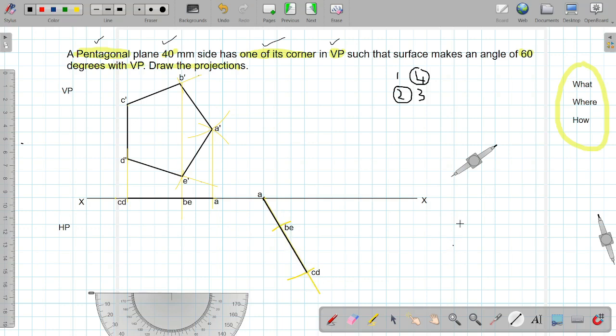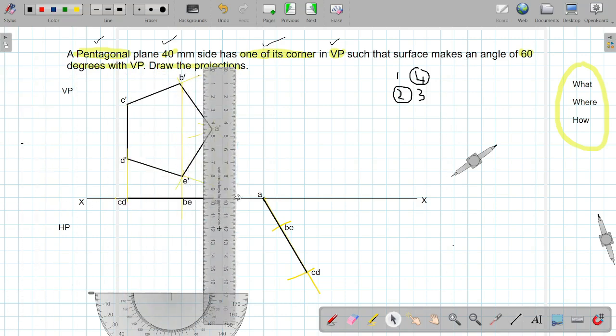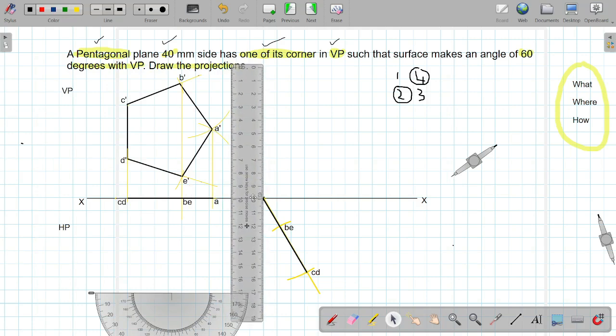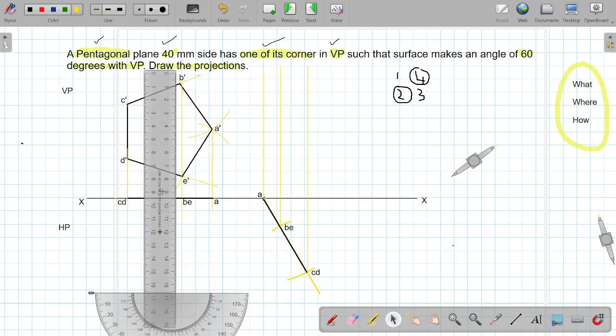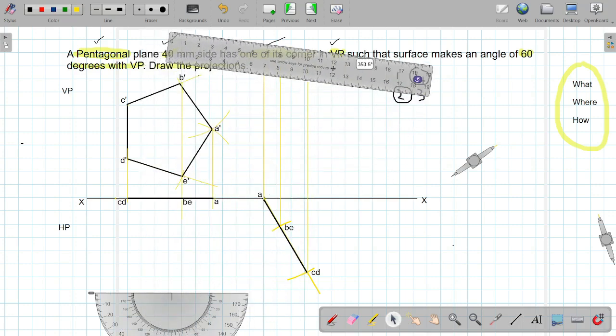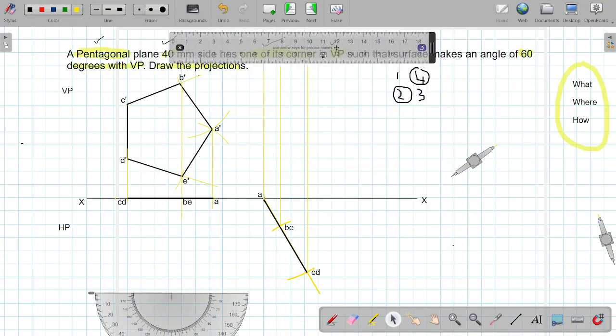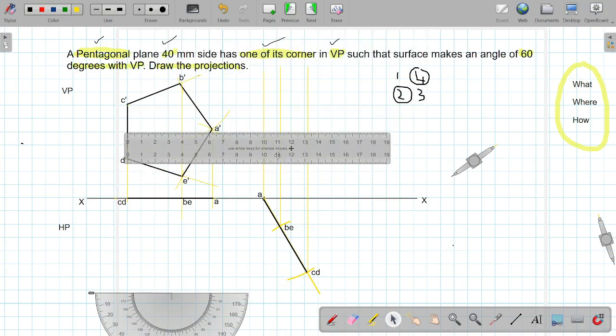Now, once this step is complete, we have to complete the solution by making step 4, the final step, and step 4 will be made by means of projections. So now taking the projections, projection should be very light. Taking projections up from all the points. Then similarly we will take projections from the front view, that is step 1, starting with point A.